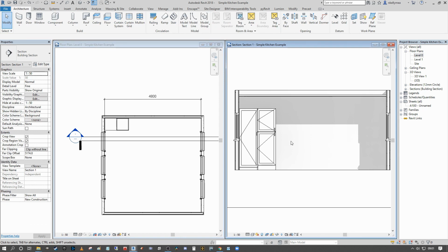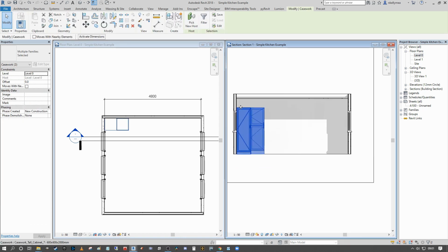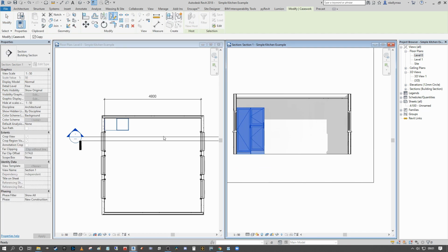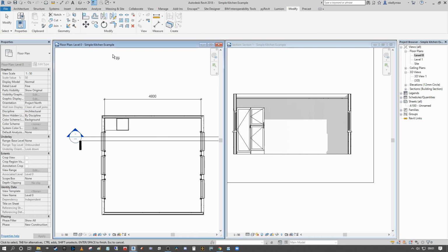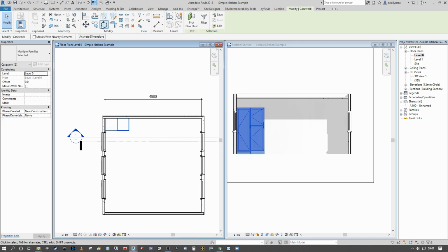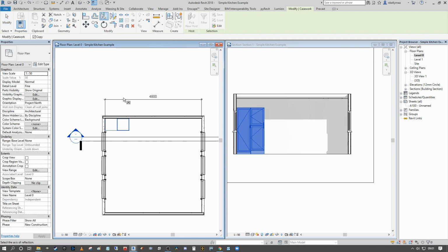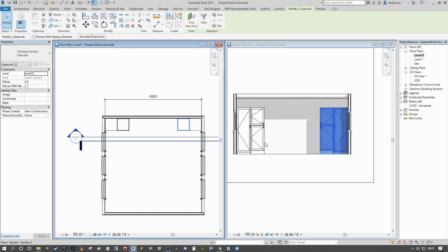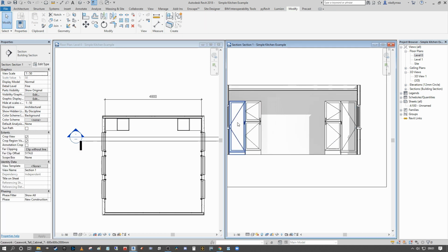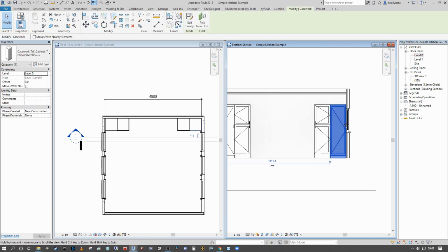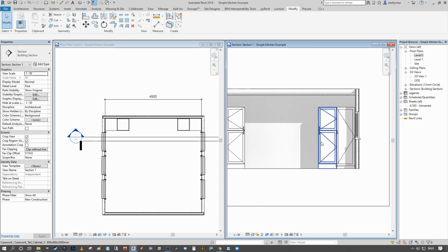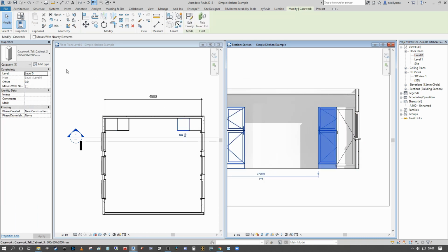What I also want to do then is select both of them, and from the midpoint of the wall here, I'm going to, apologies, I selected the model mirror tool. I'm going to pick the axis, and from the midpoint I'm going to draw and mirror them across. Okay, so we have the pantry doors there and we have the pantry door there, which is as per the thumbnail at the start of the video, and now we want to change this out.